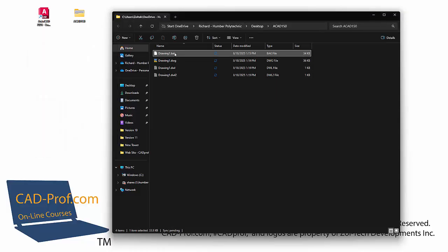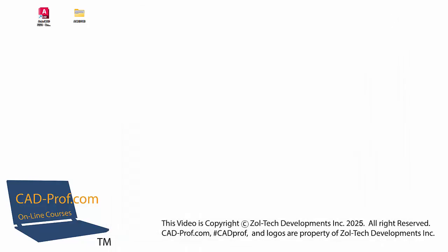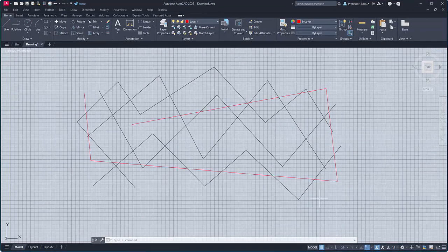So it's always one last version. Now, why do I make that point? You'll notice our 2 saves were 4 minutes apart. What I want to do, and what I want you to practice, is constantly saving. And if I know I've done work well, I may actually save twice in a row, so my backup is as current as my most current file. Those 2 drawings become exactly the same.